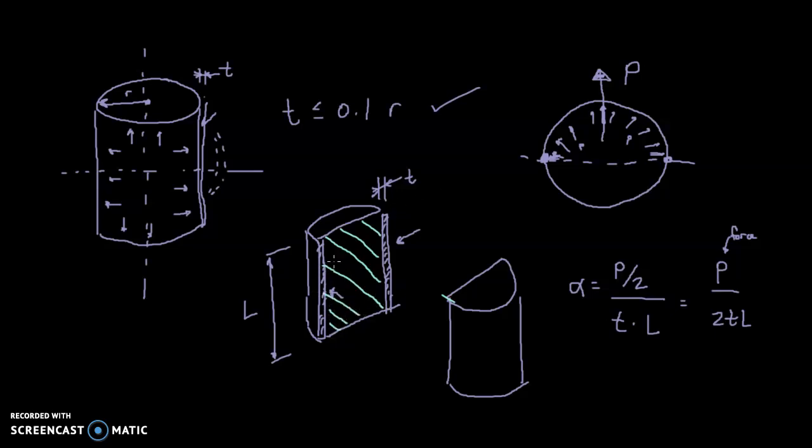So if we have this force acting on this rectangular area, which is going to have a width of D, we'll call that big D for diameter of the cylinder, the pressure times area will give us the force. So we're talking a little p pressure times a big D diameter, and we can put a little subscript i on that to represent the inside diameter, divided by the area of the rectangle, which is not just D, but D times L, our length.